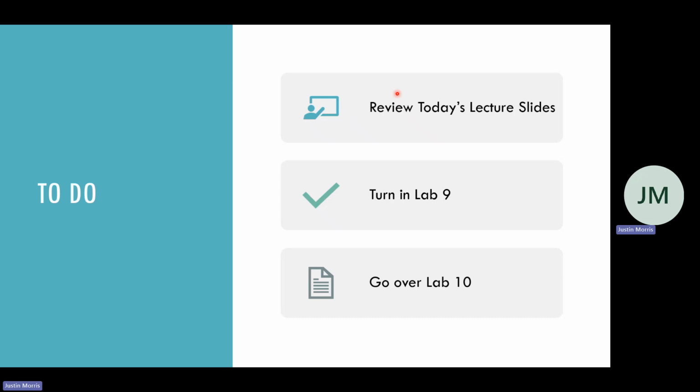Well, like I was saying, if you want to do manual checking, all your test bench does is instantiate the top level, with reset, clock, maybe a done flag, right? Set reset to 1, wait like 10 nanoseconds or whatever, set reset to 0, wait until done is 1. Right? Your test bench can do that. And then you just have to manually check the waveform that your results are correct.